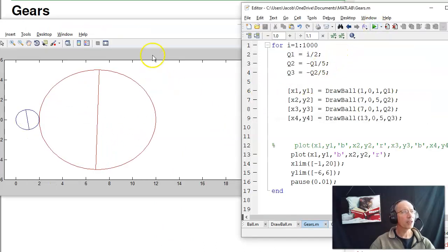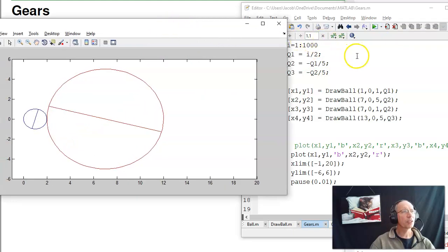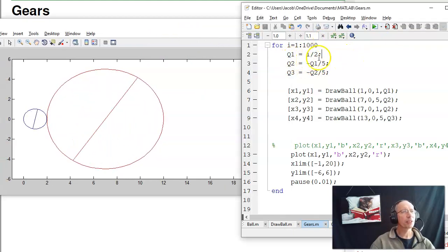And what that looks like is the following. With gears, you've got a fixed ratio. So whatever theta 1 is, theta 2 is theta 1 divided by 5 with a minus sign. At the interface right here, notice that the 2 gears are spinning at the same speed. The displacement on the small gear is equal to the displacement on the large gear. The speed changes though, because the circumference is 2 pi r. This one's got a smaller circumference, so a given distance is a bigger angle than the large gear.